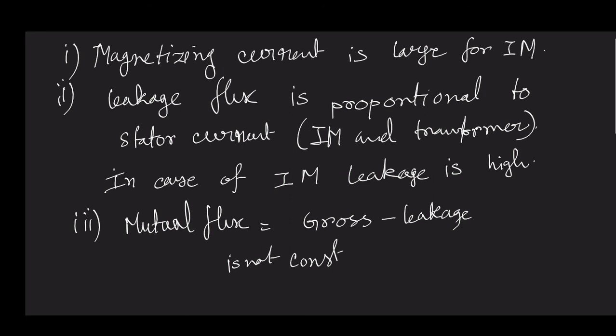But in case of three-phase induction motor, due to this large leakage, for different values of stator current, you will have different values of leakage, and that leakage is not something that you can neglect, or the leakage value is not very insignificant, but it causes somewhat, I won't say it's tangible, but some change in mutual flux takes place in case of induction motor also.